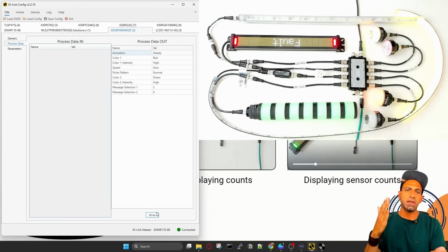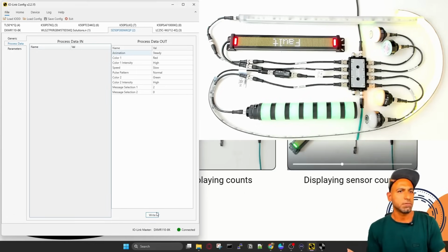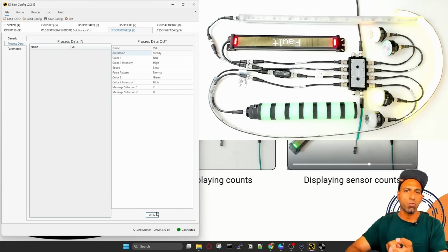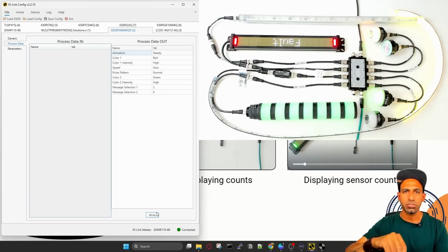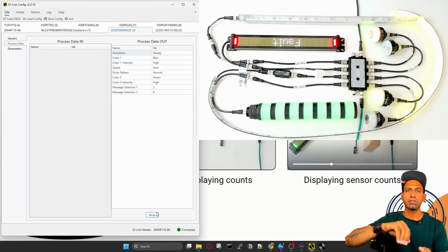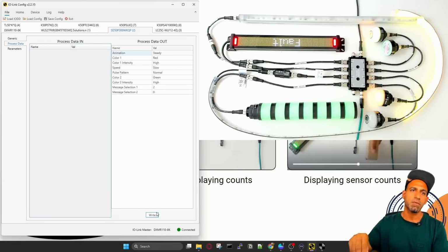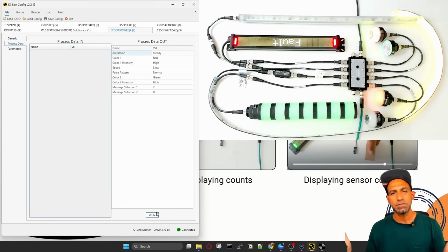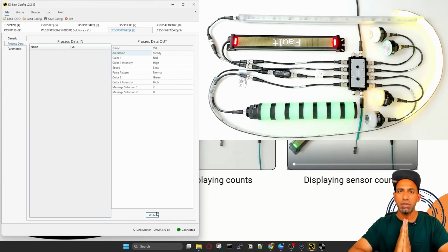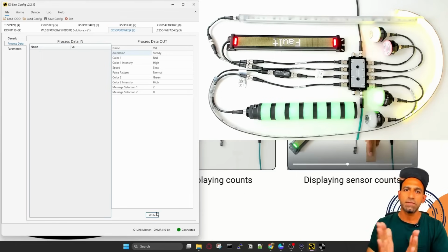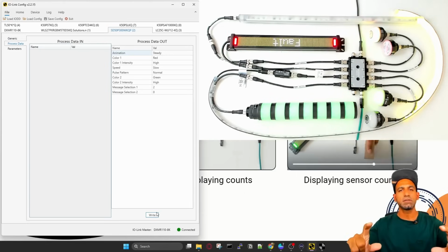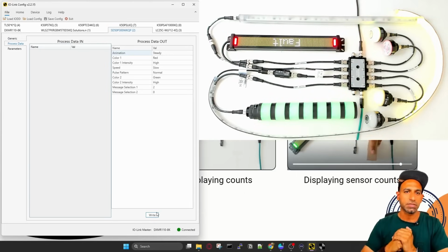So you can imagine you can have a step control of a process or maybe a robot. What is the robot doing in step number 1, step number 2, step number 3? For example, going to home position, going to pick position, pick up the object, now going to the deliver position, drop the object, coming back to the home position. These are the different steps that you can put on a status display with a cobot, so you can see what the robot is doing. And if your robot has a fault, you can also show a fault message and blink this red light so that the user can see from the distance that there is some fault which he needs to fix.